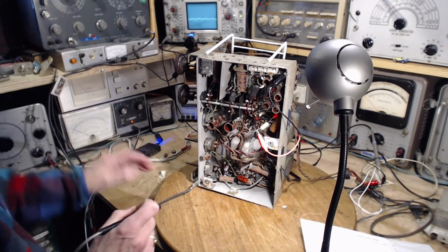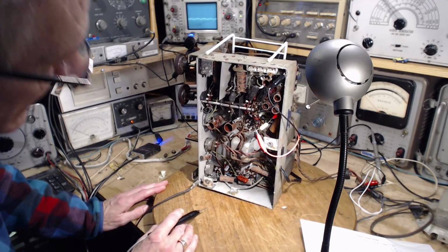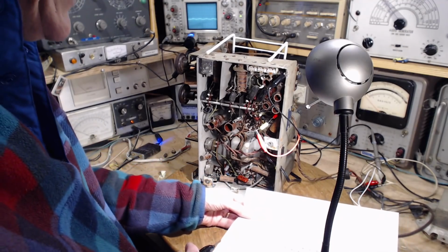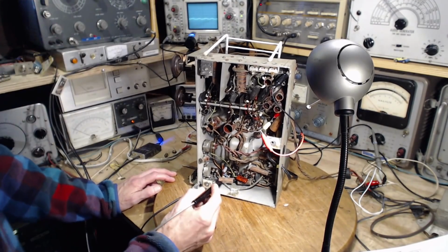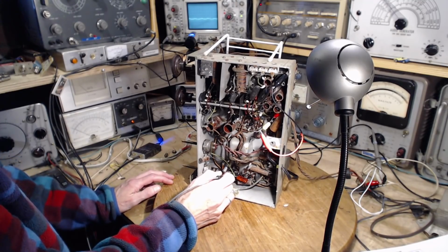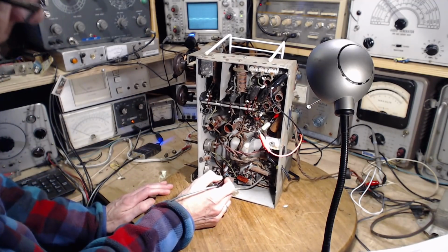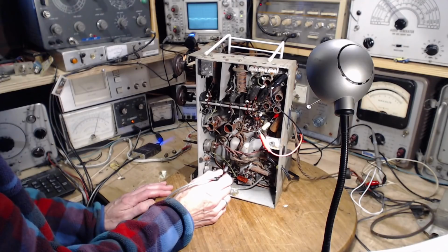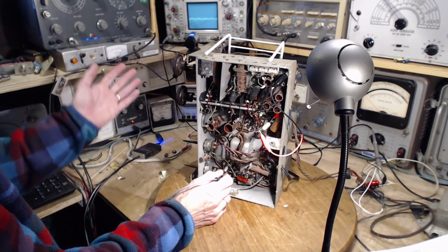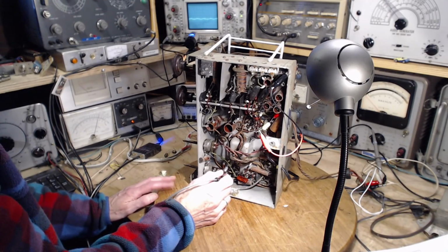This is a very important one. This is probably the cathode resistor, this guy sitting right here. So that would make that the cathode. The cathode's probably pin 8. Yep. So we're looking for 13 volts here. On a 15 volt scale, it should go all the way over. You get 11 or 12. Could be as high as 20 if the plate voltage were higher. But I think that's actually right on the money where it should be.